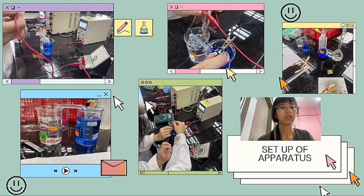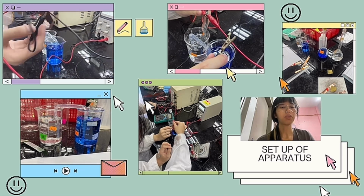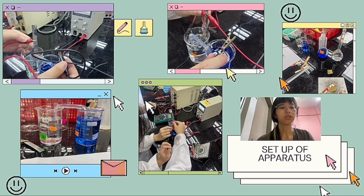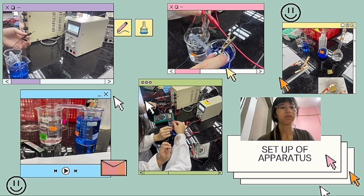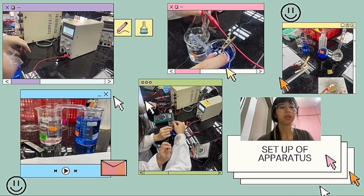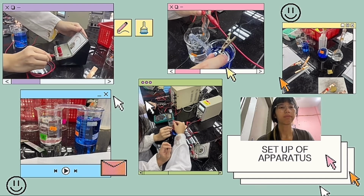The voltage was set to 1.1 volts, and the ammeter was placed in series. The setup was allowed to stabilize for 30 seconds, then the current was recorded. The procedure was repeated for each zinc surface area, whereas the surface area of copper was kept constant.